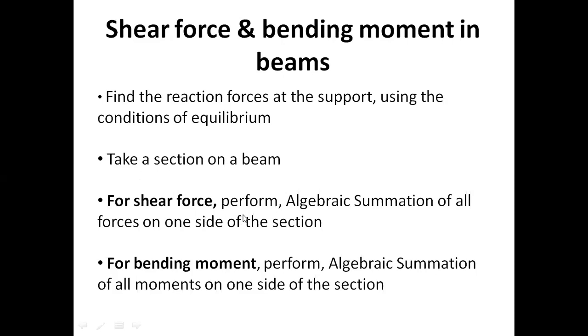For shear force, perform algebraic summation of all of the forces on one side of the section. So for the calculation of the shear force, we have to algebraically sum up all of the forces acting on one side of the section. That would give us the shear force on the beam.